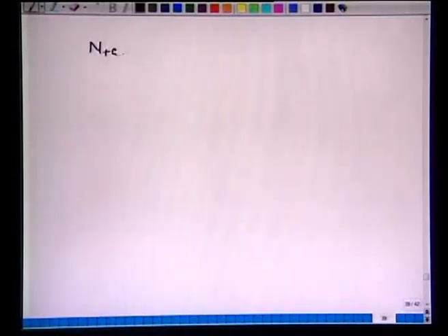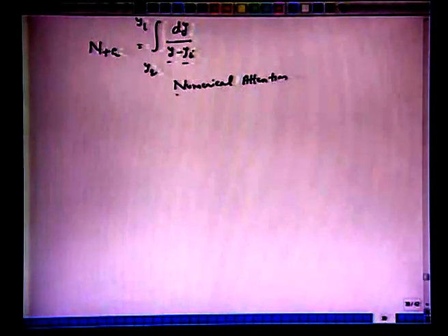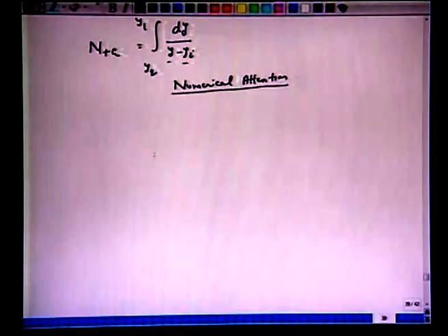So, we write down the simplified form of the NTG expression as the integral of dy over y minus yi, from y2 to y1. All right. So, this is what we are supposed to evaluate, then we can obtain the height of the column Z here. So, this integral is now between y and yi. So, this is the place where it requires numerical integration. So, you have to pay attention here. How do we calculate this quantity? The best would be to do this graphically.